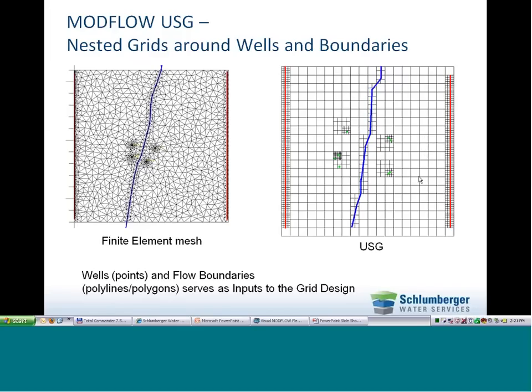Sorry, to clarify, the question was, what I mean is, on the shared nodes, what boundary conditions does the program use? To answer your question, during the LGR run, MODFLOW-LGR calculates flow and head boundaries at the interface where the child and the parent could overlap. Essentially, it generates this new flow and head boundary package, which contains heads and fluxes as the model couples and iterates between the parent and the child grids.